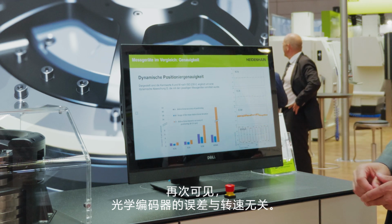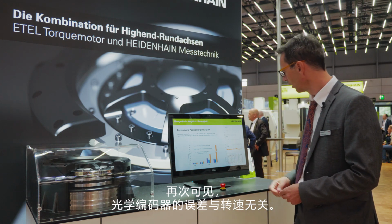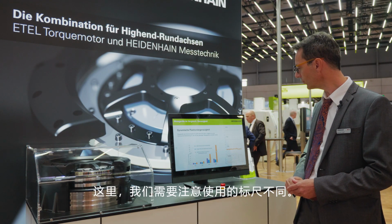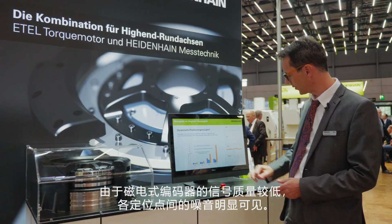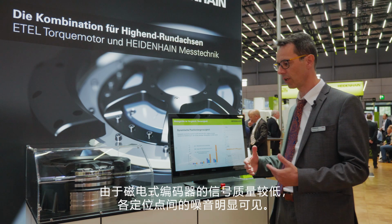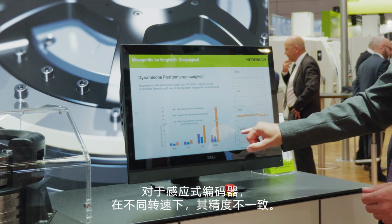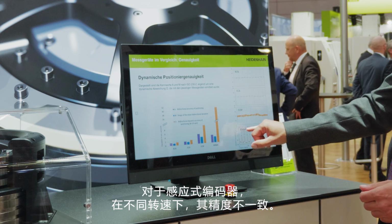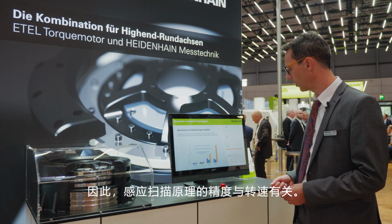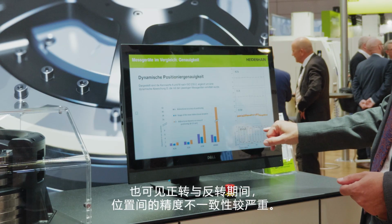Once again, the optical encoders exhibit no speed-dependent error. Here we should note that the scale is changed. Due to the lower signal quality of this magnetic encoder, noise is visible between the individual stopping positions. This inductive encoder, however, demonstrates accuracy fluctuations under varying speed. So the inductive scanning method exhibits speed-dependent accuracy behavior. This also explains the relatively wide discrepancy between positions during forwards and backwards motion.